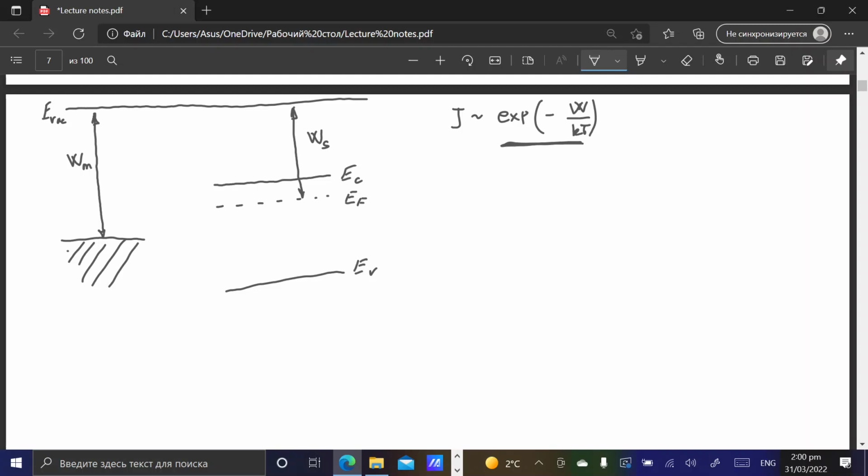Initially, in the neutral case, before the contact with the metal, the total net charge of this semiconductor is equal to 0. If part of the electrons are gone, then at the interface we will get some positive charges associated with immobilized donor centers in the crystalline lattice. They will just not be compensated by electrons because they are gone.